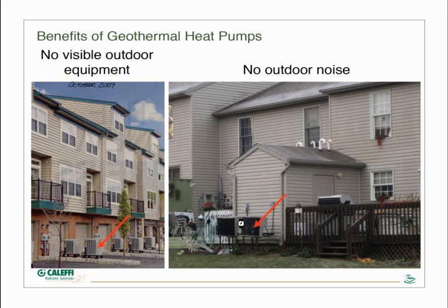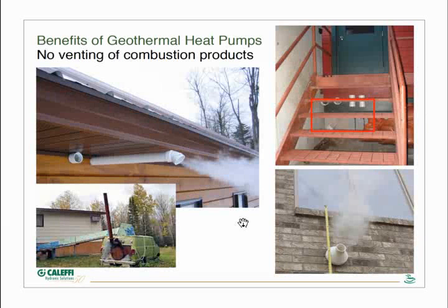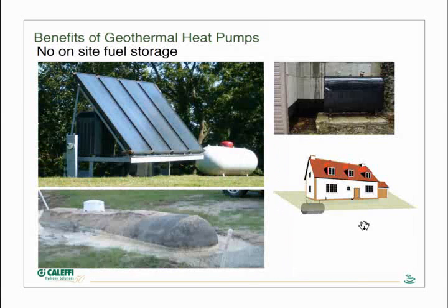Obviously, heat pumps don't involve combustion. And as such, we eliminate any issues with venting combustion products, whether it is how to get those vent tubes out of the building without producing these plumes. This one in the upper right is one of my favorites. I'm not sure who did that, but that's not really a good idea. You're going to have a lot of ice on those steps if that's a cold climate. And down in the lower right here, again, somebody that wasn't reading the installation manual as far as clearances to windows. So this all disappears with heat pumps, as does on-site fuel storage.